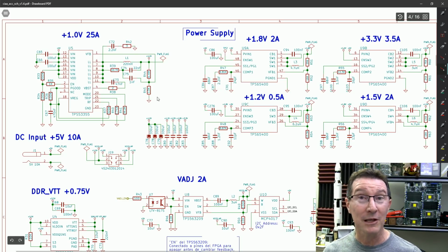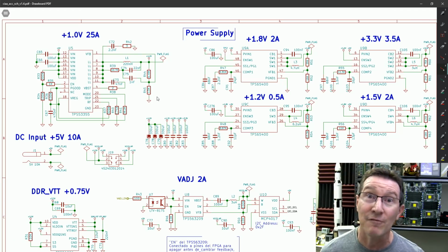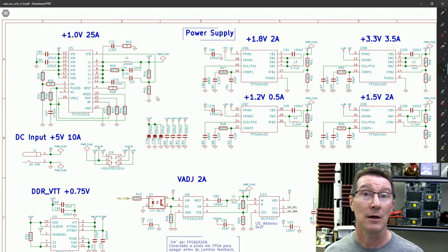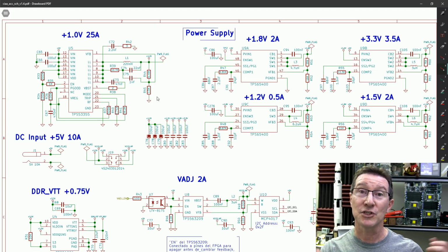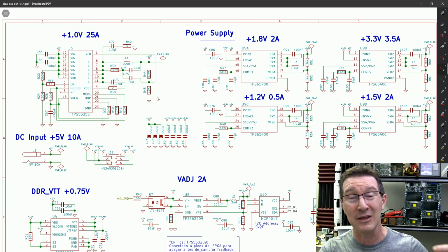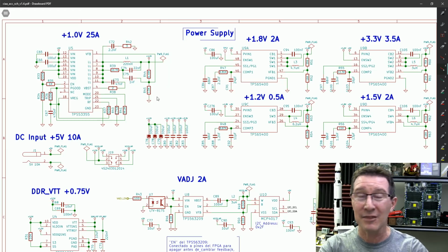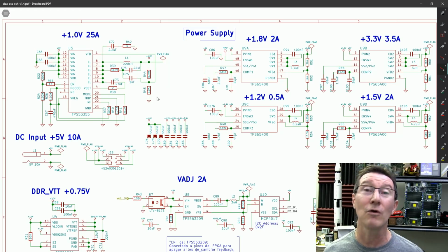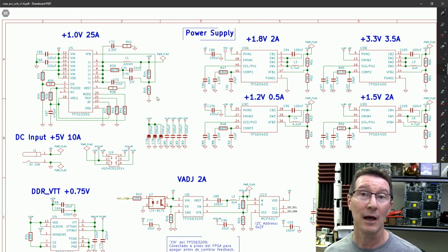But I decided just to show you, in this case, 3 different ways to consolidate your BOM. And it's not applicable to all designs. You may never get to that stage where you need this, but if you want to level up your skills in electronics design, then BOM consolidation can be a vital part of your design for manufacturing process. It's an essential step in your design. You draw your schematic, you do your BOM consolidation, then you do your ERC, and then you lay out your board, and then you do your other design for manufacturing stuff, in whichever order you want to do it. It can be really important.